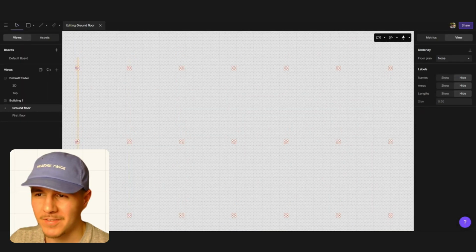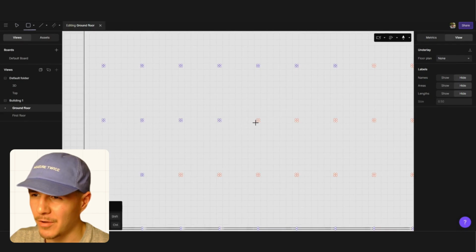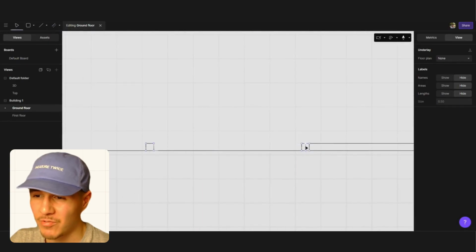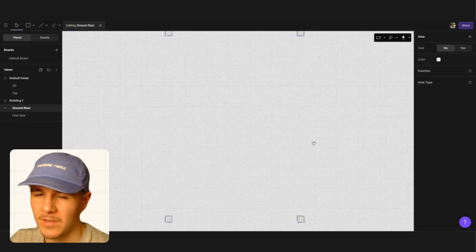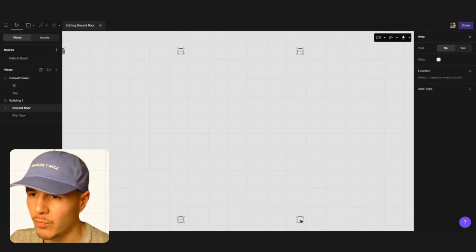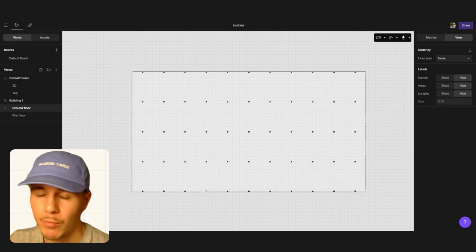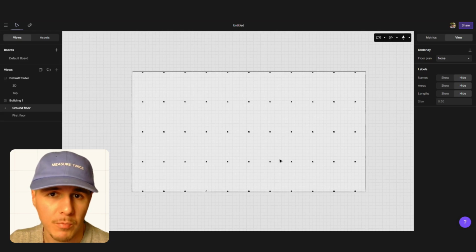Here I made some mistakes. This is going back and forth. I was trying two different techniques, and then I locked one in midway through. There are much faster ways to do this. I think the best way would be to just offset the lines and then delete what's excess. The cool thing is that when you offset lines or create lines, automatic points are created, which are pretty logical, and it means your lines are automatically cut and you can just keep the shape that you want within those lines.